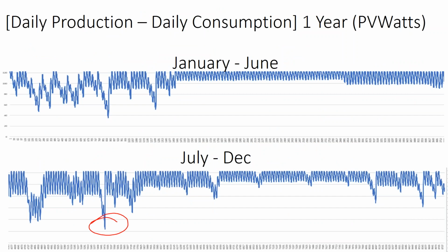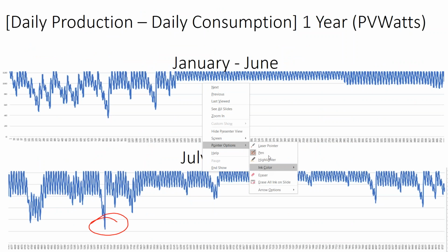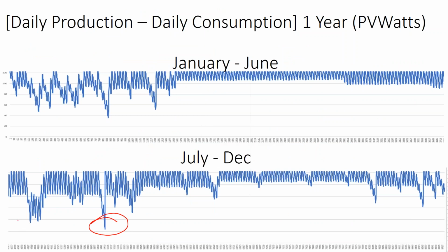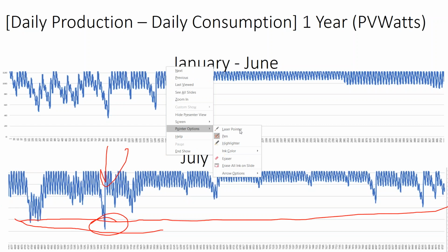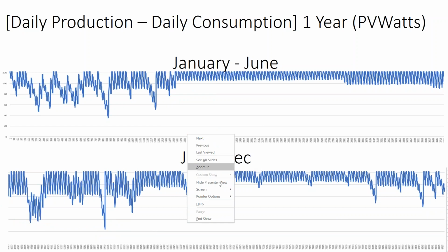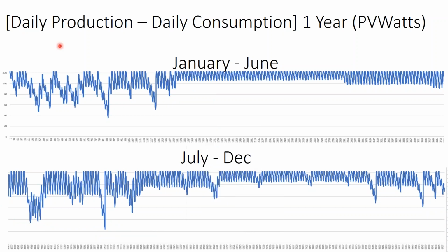We looked at how much energy is coming into the battery bank versus how much energy is coming out. We looked at, on a regular basis, not wanting to get down into the bulk phase. For all the days of the year except one, we're in the absorb phase. So for the client's parameters, it's a well-sized battery bank.